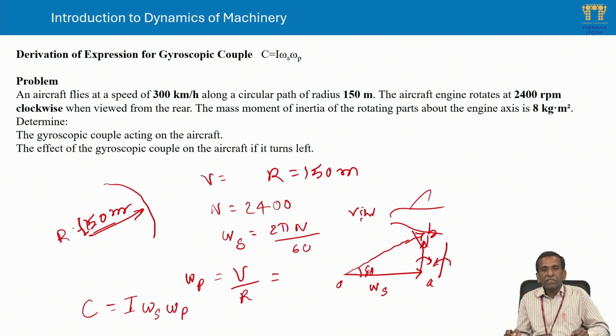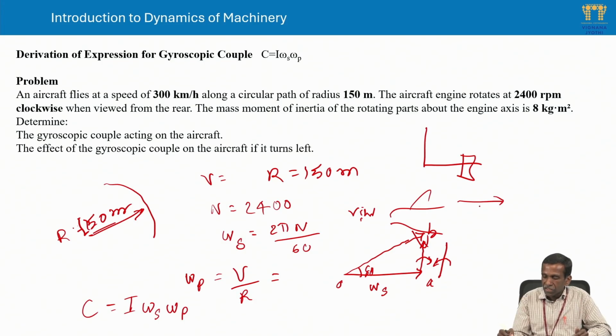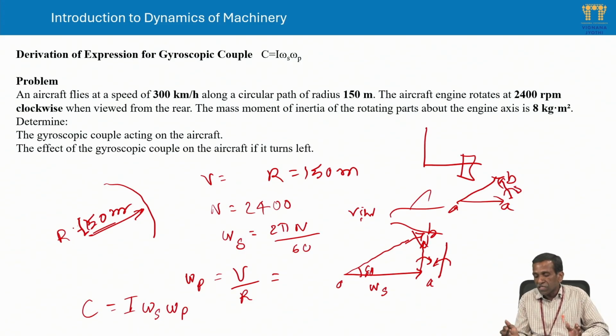These problems are very simple to attempt, but once you understand the way, you can see the rotating body has a vectorial representation. The spinning axis is given an anti-clockwise rotation. Then the change from starting A to B vector is the gyroscopic couple, which is vector A to B only if you rotate clockwise. So the reaction is in the opposite direction, B dash to A dash.